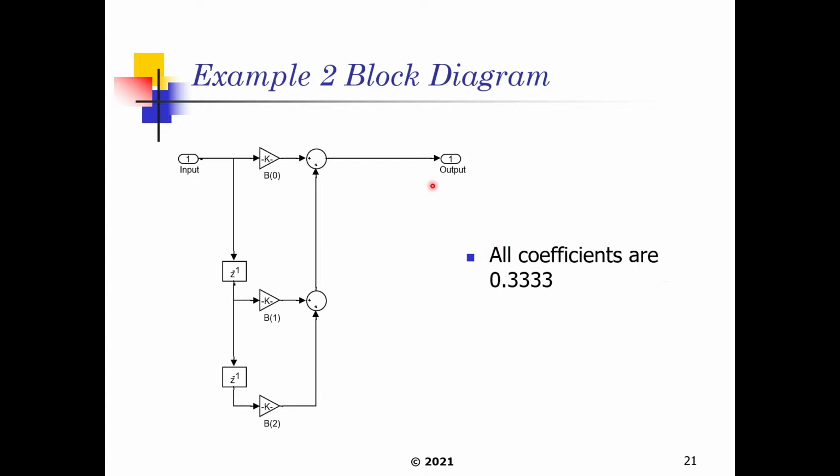If we need to draw this as a block diagram, this filter here is basically a feed-forward filter design. So we basically have our first level here, then our second level, and then our third level here, where each one of these delays here are matched accordingly. In exam calculations, you can just write f of s divided by f, where f of s is the sampling frequency and f is the first null or zero crossing frequency. You don't need to do the derivations.